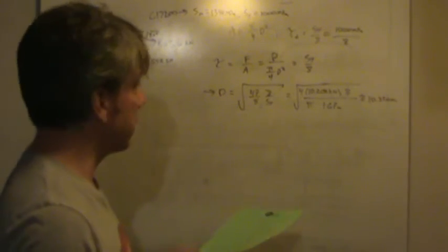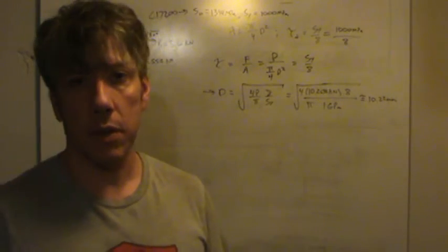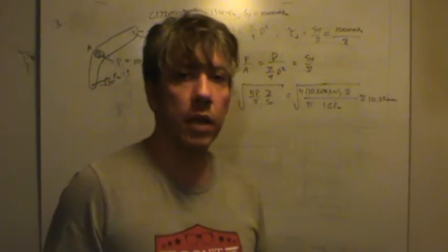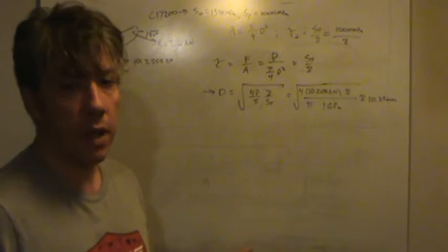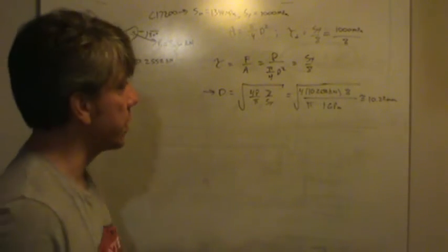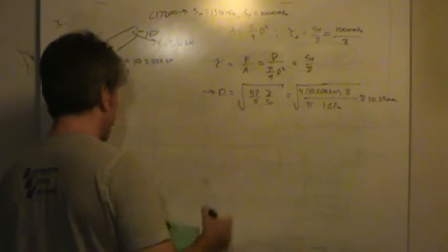Okay, well, you don't want to specify a pin that size. You can't get one that size. That's not standard. You'd have to have it turned, and that's expensive. So you go up to the next basic size, and I'd recommend not going to the secondary basic sizes, but the primary. I forgot what they're called. But anyway, they're in your book.